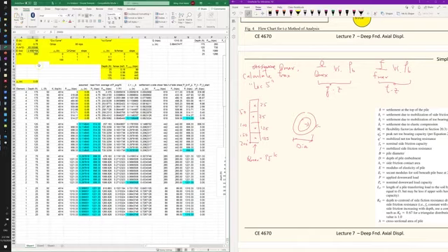We also know the stiffness, the elastic modulus of the steel pile here. It's 29,000 ksi for this pile. We need this information to calculate the elastic compression, and the whole length again is 200 feet. We also have the QZ and TZ curves, and this is the coding that we use for the QZ, and then this is the TZ.